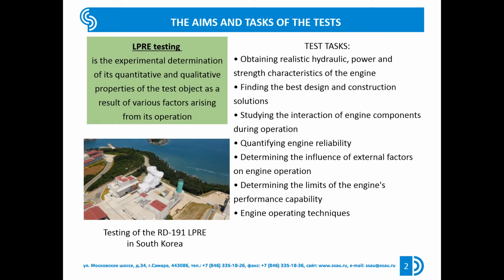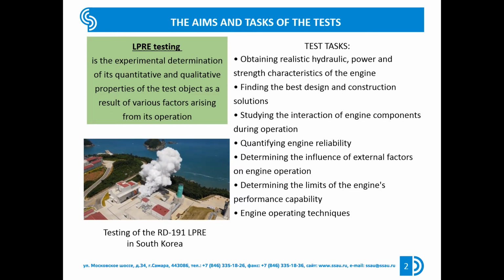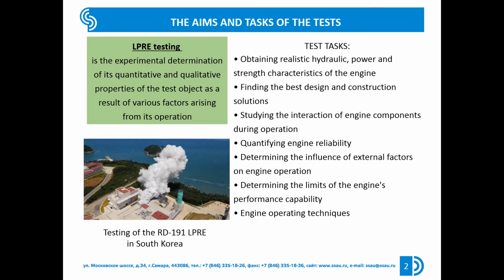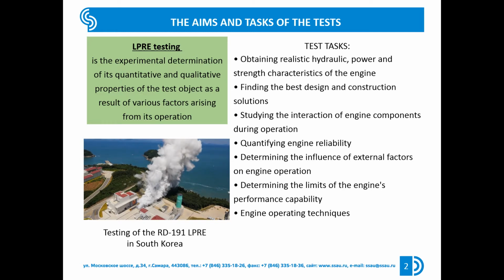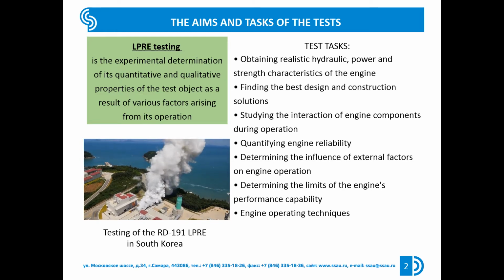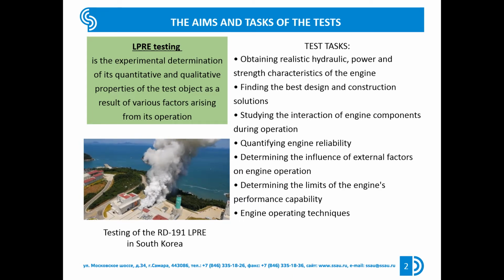We begin, of course, with a definition. Testing is the experimental determination of the quantitative and qualitative properties of the test object as a result of various factors arising from its operation. In the case of a liquid propellant rocket engine, the main purpose of testing is to assess the performance of the engine's technical systems and to investigate the processes that occur in the engine.